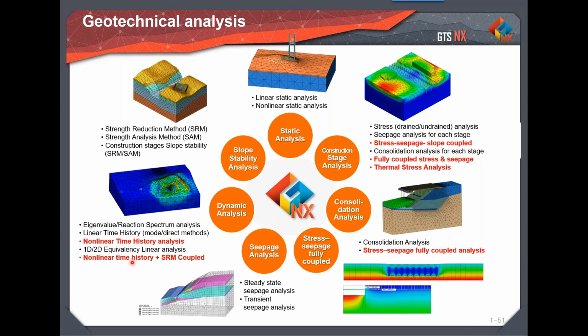And at the end of the earthquake, or maybe during the earthquake, you want to study the slope stability of that particular slope or particular excavation area. You can couple your SRM with this linear time history, and at a particular time of your interest, you will get the factor of safety and the corresponding failure surface as well.